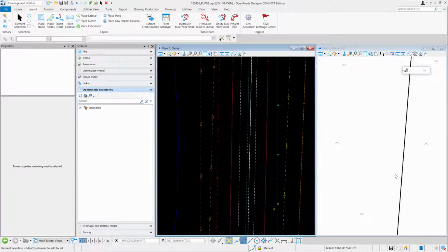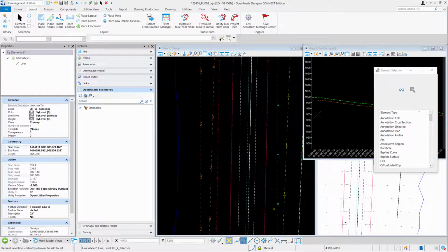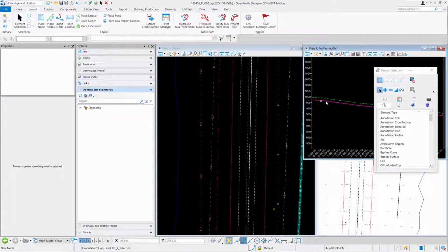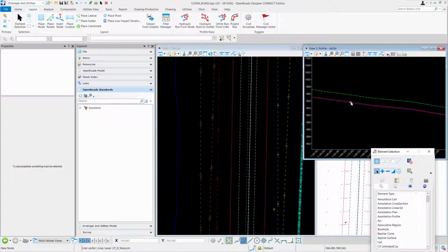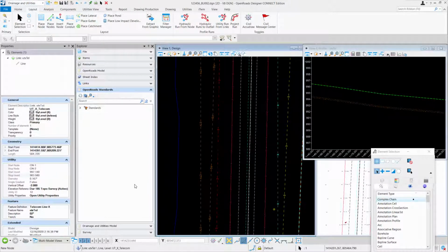So there it is. It extracted that in 3D. I can click on this pipe, open up the profile of this pipe, and you can kind of see there it's following the surface, offsetted at that depth that we defined. If I take a look at the properties, you can come in and change this offset at a later time if you want to. On my next video, I'll go over more with editing profiles and making custom profiles, so check that next video out for things like that.